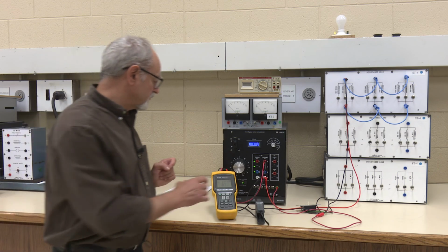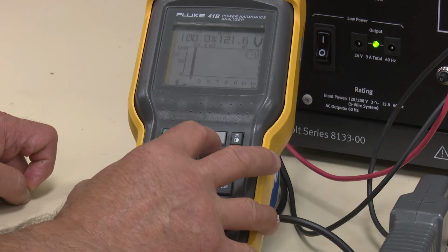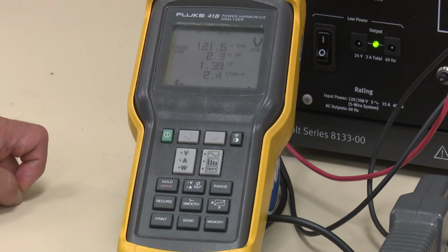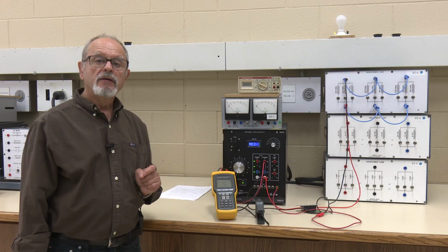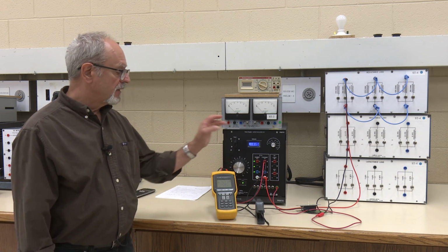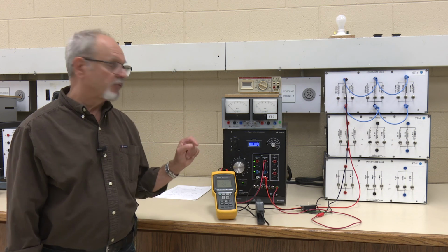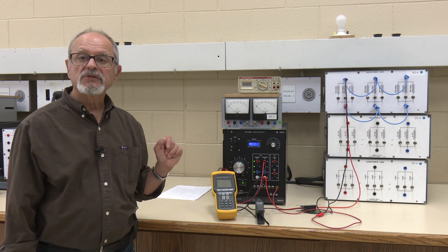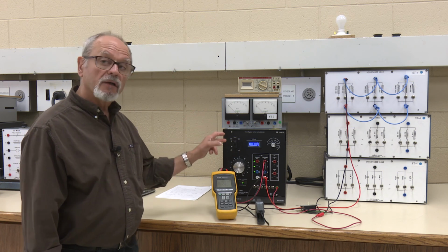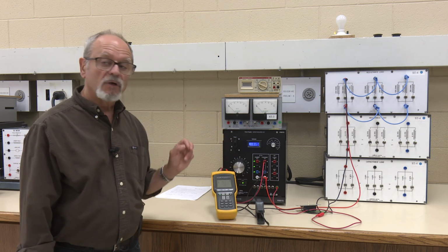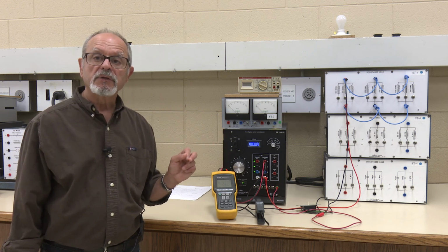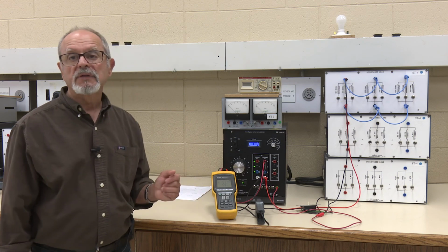Now, just for fun, let's have a look at the harmonic distortion on the voltage. And we see it's only about 2.1%. We can live with that, but again, keep in mind that this is a very tiny load that we're drawing off a rather big supply. If, on the other hand, the supply was not an infinite bus and the load was substantial, then the distortion on the voltage would be considerably greater, to the point where it would probably exceed 3%.